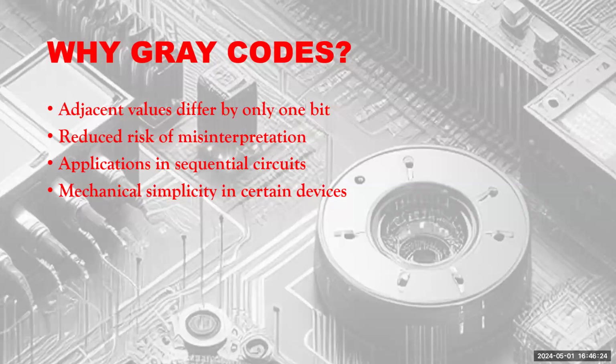There is a massive transition. And similarly, at other points, when you switch from 7 to 8, etc., there is massive flipping happening. Most bits are changing at those times. Why is that a bad thing in some circuits? When there is a massive amount of transition like that, the energy impulse is very high at that time. So it causes energy disturbance.